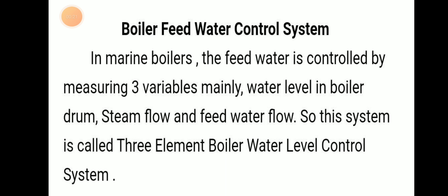In marine boilers, feed water is controlled by measuring 3 variables: the water level in the boiler drum, steam flow, and feed water flow. Because of this, the system is known as the 3 element boiler water level control system.